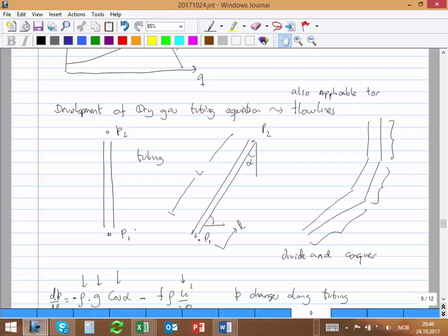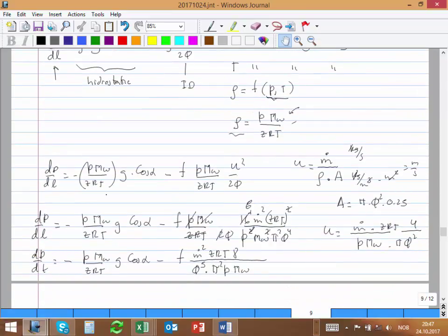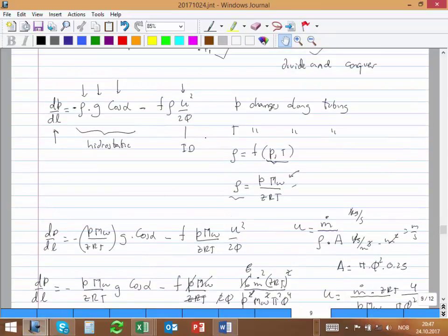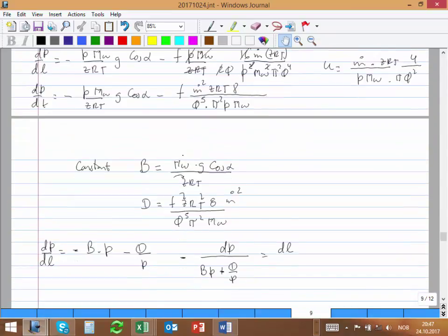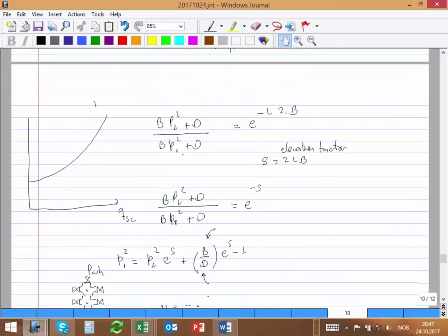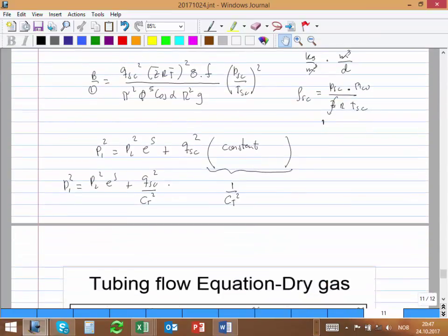And then we went to the derivation of the tubing equation, and this equation is valid for constant diameter and constant inclination. If your well has some differences, then you have to split it into sections and create CT and DS for each section. We derived it from the equation we know, the Bernoulli equation, and some mathematical tricks. And we reached that equation, and we haven't plotted it yet to see how it looks, but we suspect it's going to look something like that. That's what we expect, and let's see tomorrow if that's how it looks.